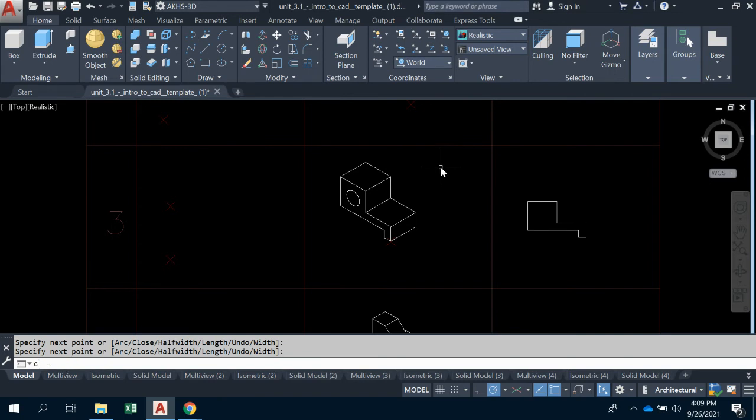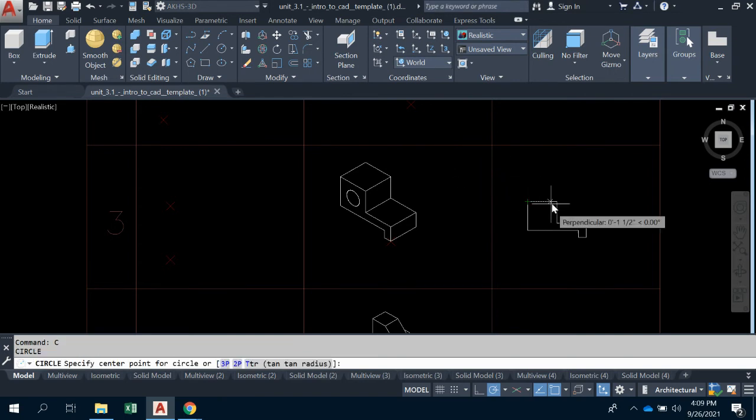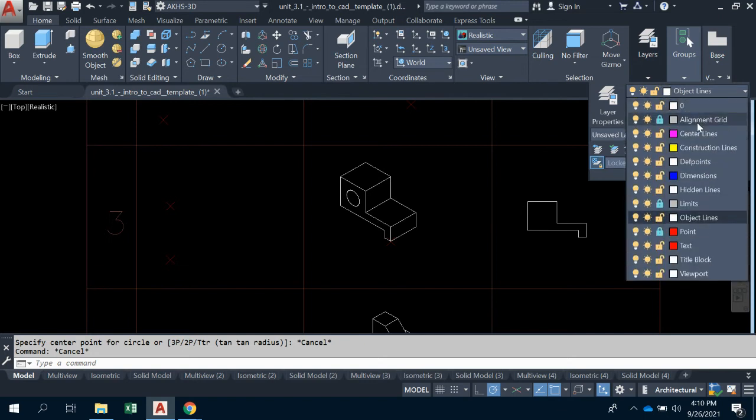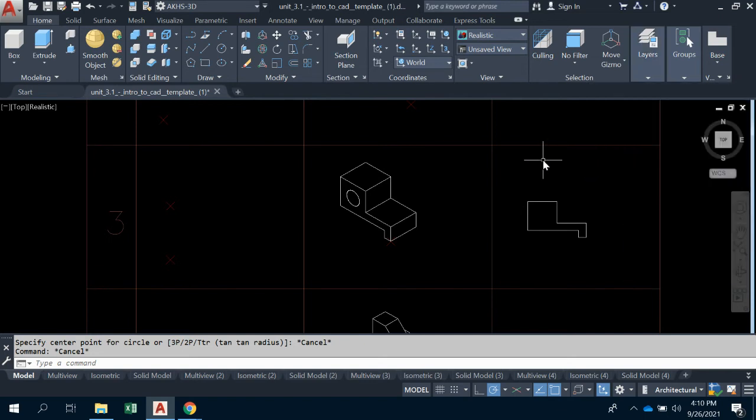Next, we are going to draw a circle. We can try to draw that circle without having to draw lines, which doesn't always work, which is fine. If that's the case, one little helpful piece is to switch to a construction line before you do that. And then we'll draw 2 lines, one from here to here.